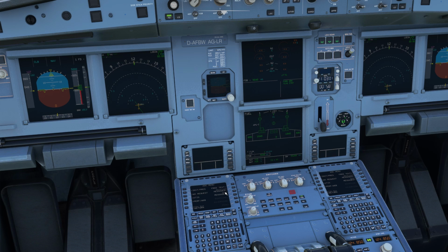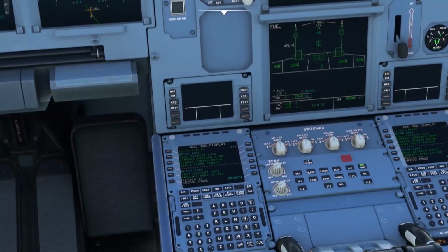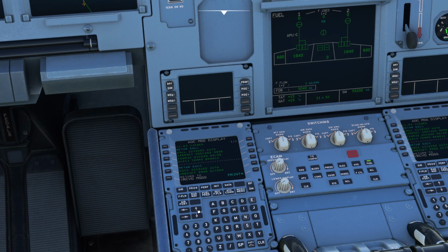We'll wait to click on it, because if you click on it before, it sort of delays the message coming through. And there it is, company message. So we're now going to click received messages, and there it is, the METAR. Having a look at the METAR, we can get the information that we needed for the approach phase of the perf page on the MCDU, as we went through before.